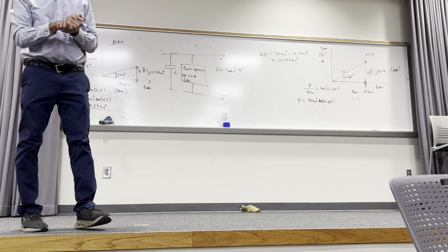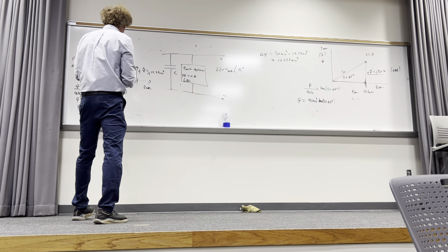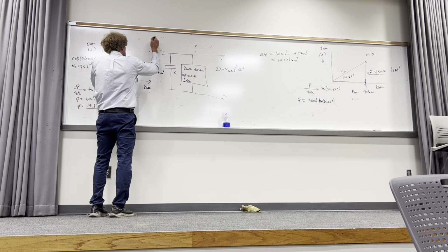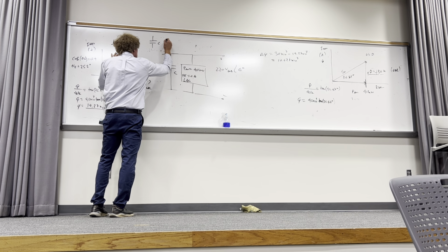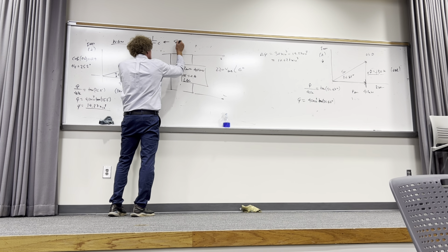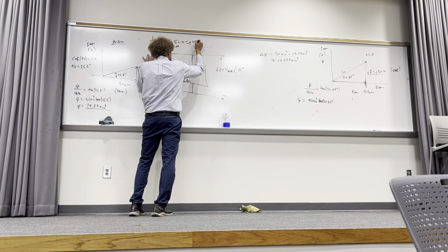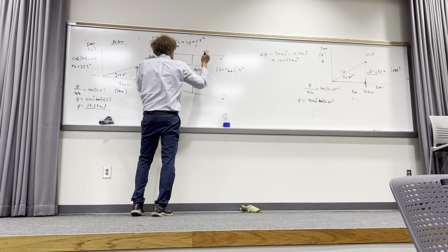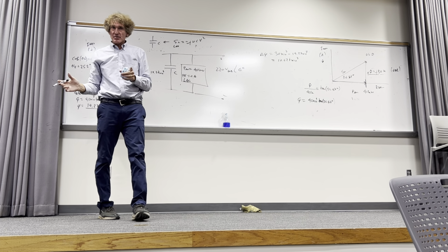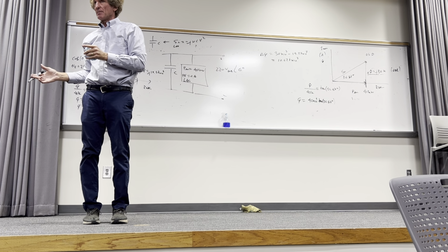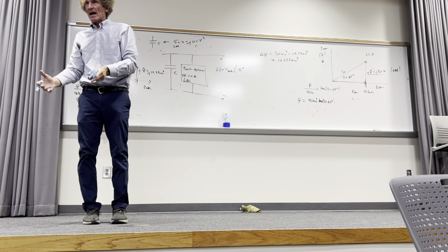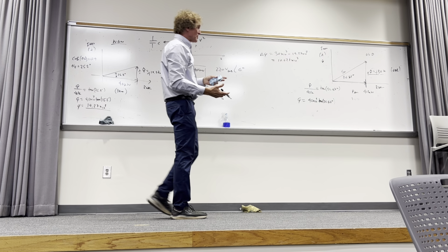And I know for that capacitor, the complex power associated with the capacitor, I'm just going to put it here. This has a complex power equal to minus J omega C times the voltage squared. Y'all with me? I'm just putting it down there so it rings bells and you keep it. I know that added to a positive J would reduce it.